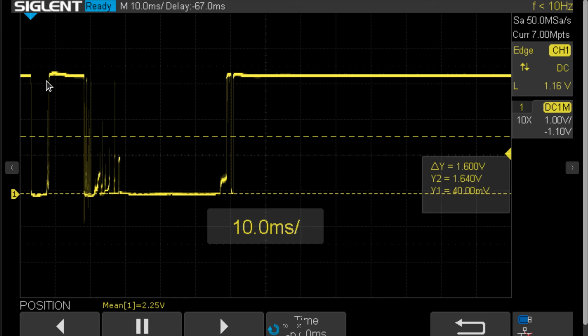And when that happens, we're going to just reset our whole logic. We're going to say, well, that must have just been a lightning strike down the road or something that caused a little spike. We won't see this at all in our output. It'll go back to where it was. Everything will be copacetic. We'll sit there and we won't do anything. Then it'll change again. It'll go from 1 to 0. It'll go, aha, it's changed, but it's bouncing back and up. Well, no, okay, we're not going to care about that. It'll come back up here.